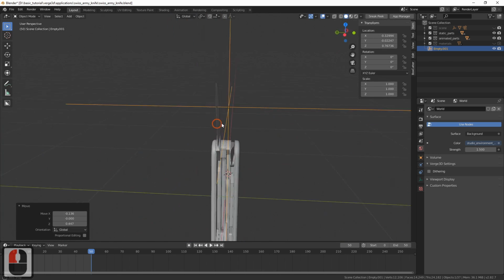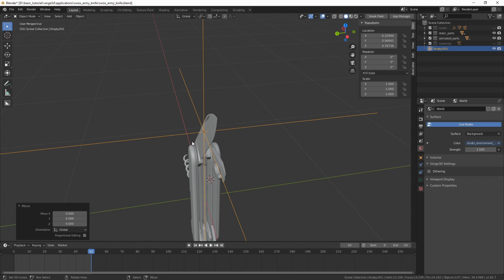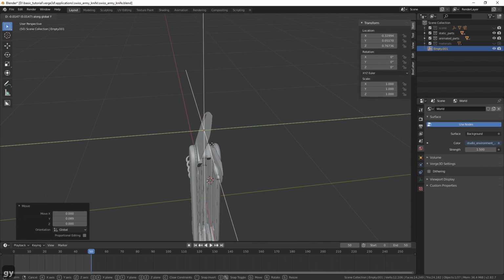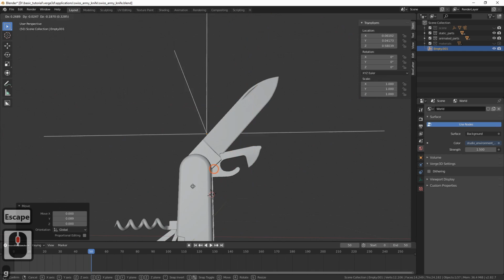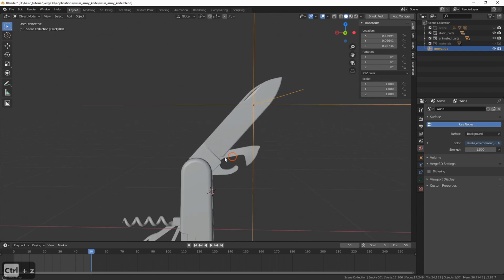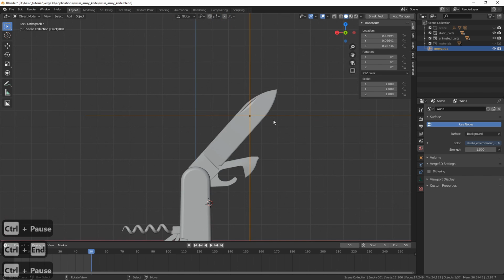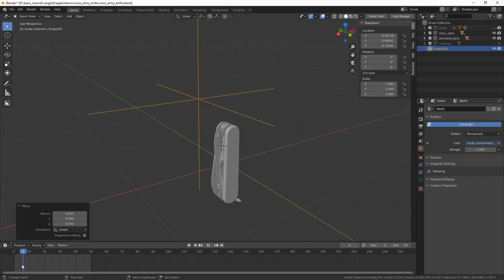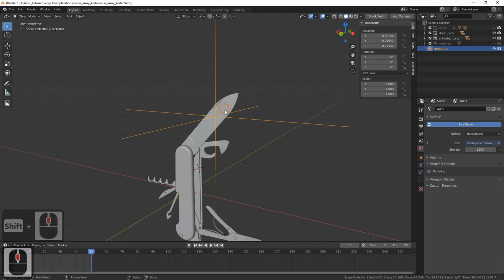Okay, here is the first big blade. Let's place its empty in such a spot where the geometry would not obstruct the annotation. The empty should not be placed inside geometry, nor deeply between objects, but rather in an open, readily observable location like this. Since we are dealing with an animated object here, the empty should be attached to it, so that they move together.